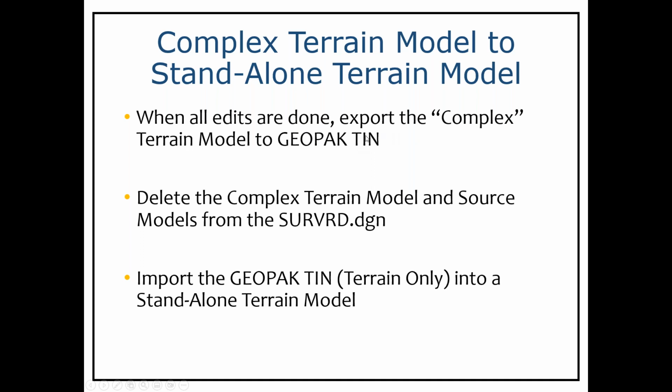Being able to edit them with survey processing on is probably not as critical, but it can make sense in some situations. When all edits are done, you can export the complex terrain model to a GeoPack 10. Then you can delete all those complex terrain models, and it could be quite a few that get put together into it. It really can get somewhat confusing. And then you can just import that GeoPack 10 back in as a standalone terrain model.